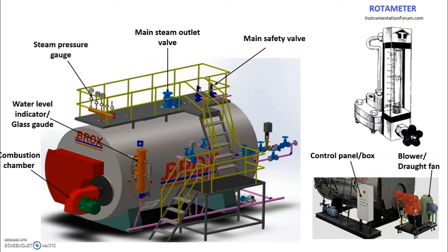When it exceeds its limit and the steam outlet is not open, meaning the heat is contained in the tube and is exceeding the limit it can hold, the main safety valve will open automatically. Most of the time, the main safety valve is connected to a chimney. So it opens to the chimney so that the steam will pass through that place.